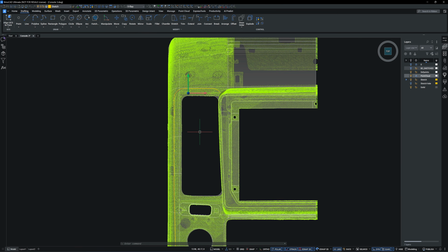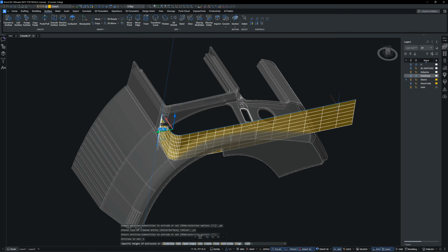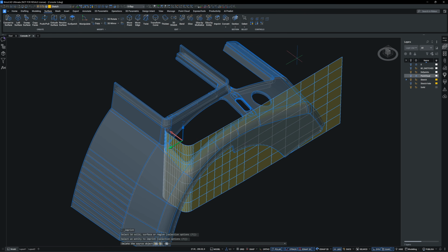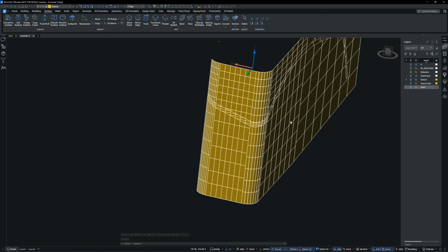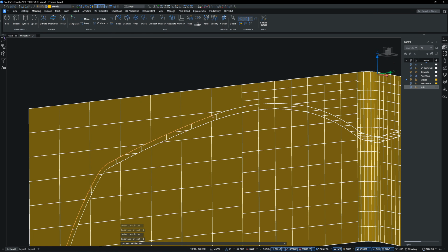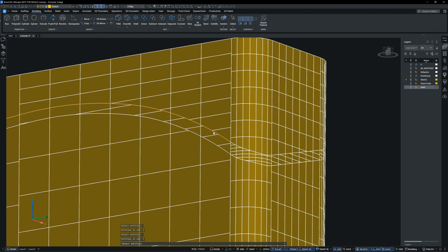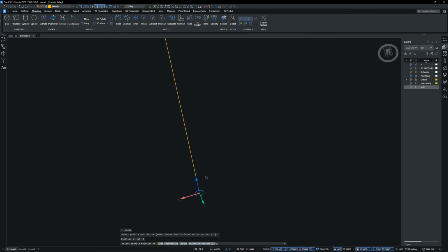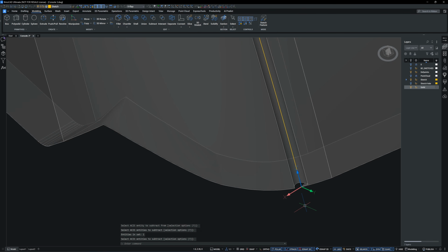The tricky part here is generating the 3D curve directly above the surface. First, I extrude a surface from a flat sketch. Then I use the imprint command, select the surface first and then the bezel. This command creates an imprint on the surface. Then I use the extract edge command to pull 3D lines directly from that surface. The 3D lines lie exactly above the solid surface, which makes them perfect as sweep paths for cutting the embossed profile.